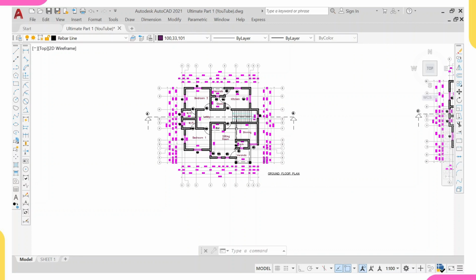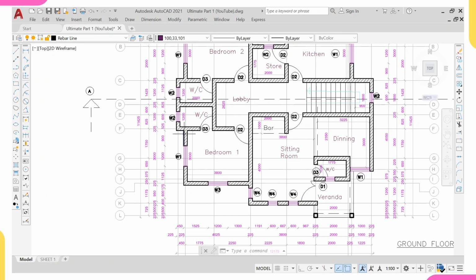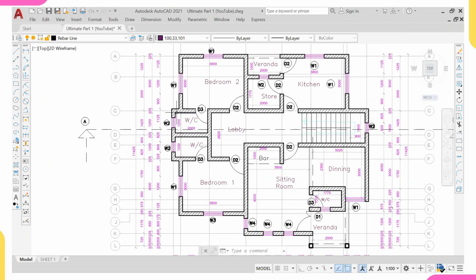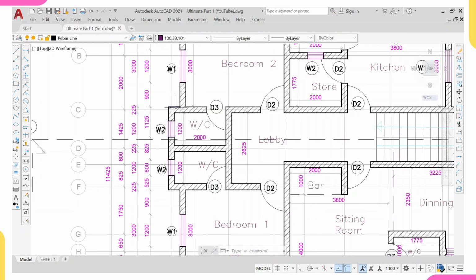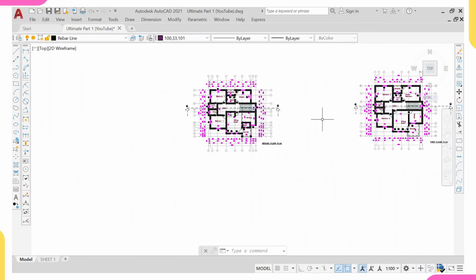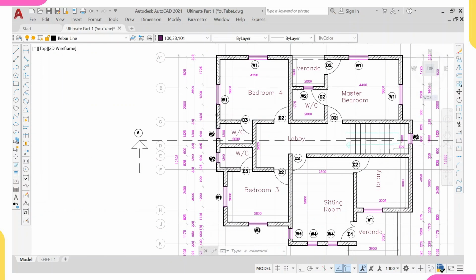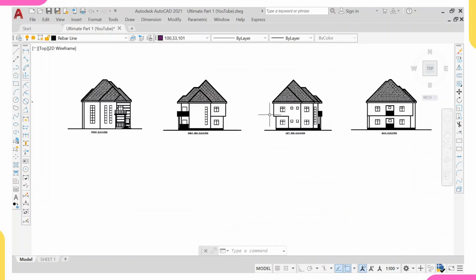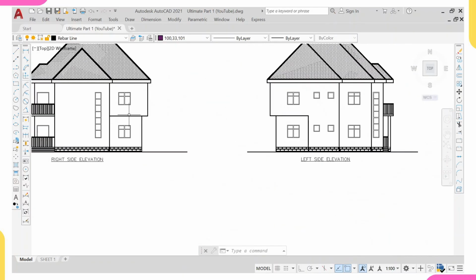Another reason why I study the architectural plan is to know whether there are cantilevers at story 1. So for example, look at this. These are toilet and bathroom. If you see, there is an offset backward, but if you go to story 1, you can see it's a straight line, so it's moving straight. That means we have a cantilever at story 1. This is the cantilever, this is the cantilever.